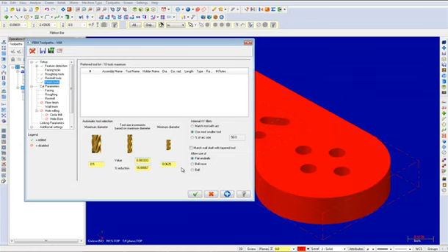Use Next Smaller tool selects a tool that is the next size smaller based on your automatic tool selection settings. If Mastercam must create the tool, it creates a tool the next smaller standard size for the tool type. And finally, percentage of arc size selects or creates a tool no larger than the percentage of the arc you specify. Once your parameters have been adjusted, select the facing page.